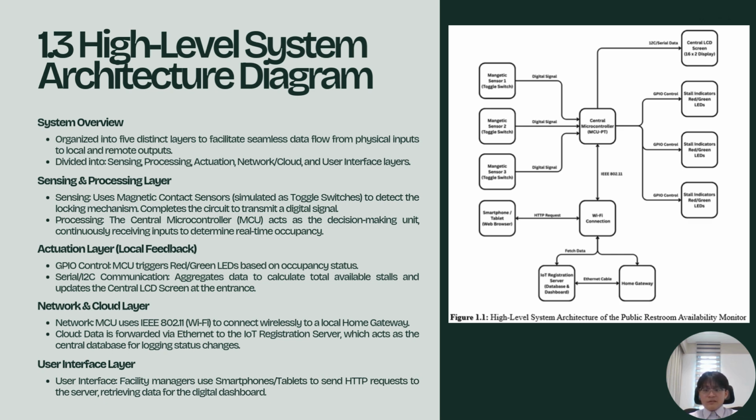This sensor detects the locking mechanism of the door. When a user locks the door, the sensor completes the circuit and transmits a raw digital signal up to the next layer. So next is the processing layer. The component here is the central microcontroller, or what we call the MCU. This acts as the decision-making unit of the entire system.